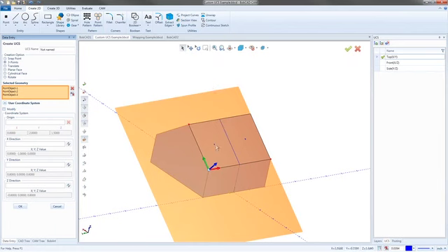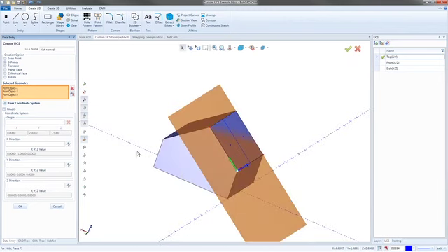So now if I was to go and put holes on this part, like where these 2 points are, and I was to do an extrude cut, it's not going to be an extrude cut based on the arc being flattened to this, an arc coming out this way. It's going to be an arc that's normal to that surface. So the big thing here, and it's the thing I always forget, especially if you're used to version 30 or previous making UCSs: if you used the 3 points in the past, after you clicked all 3 points, the UCS was made. In this one, that UCS is still orange because it's not done yet. We haven't fully made it yet. So I'm going to just rename the UCS so we know what it is. I'm just going to call it holes UCS.